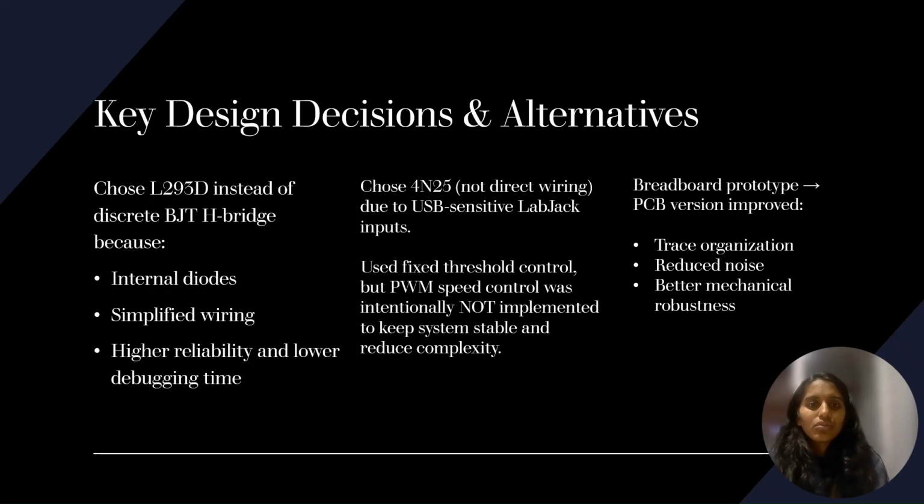For motor control, we kept the design simple with an on or off control instead of PWM speed control. The goal was stability, not complexity. And finally, we started with a breadboard prototype and later moved to a PCB. The PCB version reduced noise, improved connections, and made everything mechanically stronger.